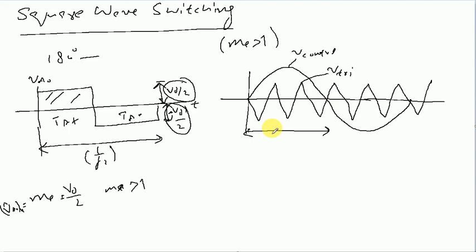We had also discussed this when we discussed this category of voltage source inverters, that in this particular case the inverter will not be able to regulate the magnitude of the output voltage. So it is necessary that we regulate the source, the input DC voltage, because now the output depends completely on the value of VD by 2 in both of these magnitudes, so we need to regulate that particular voltage to have the desired value at the output.